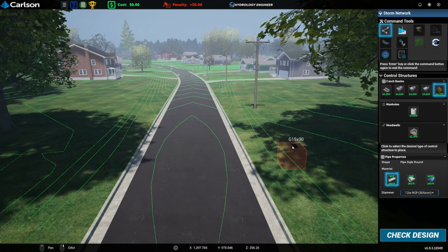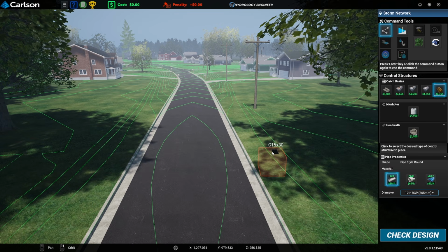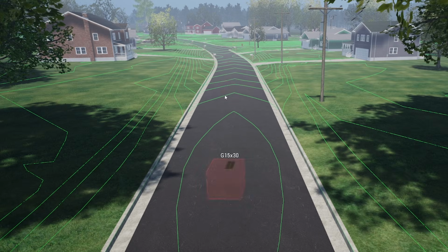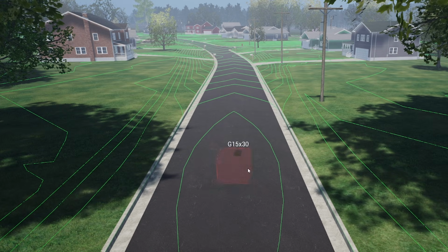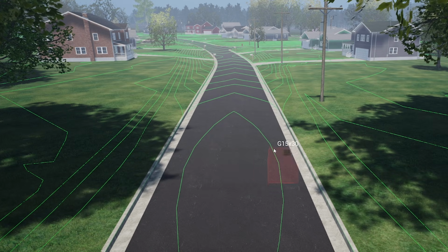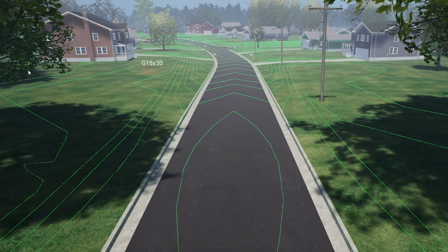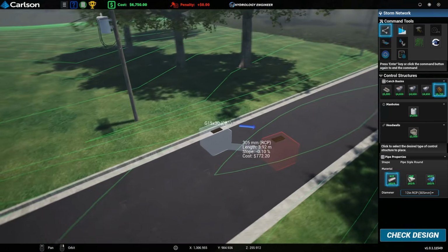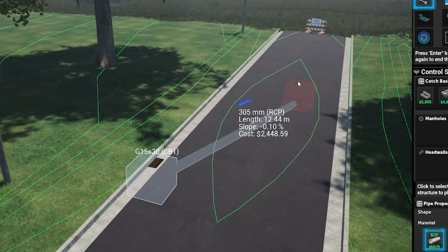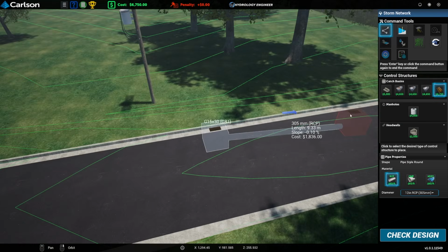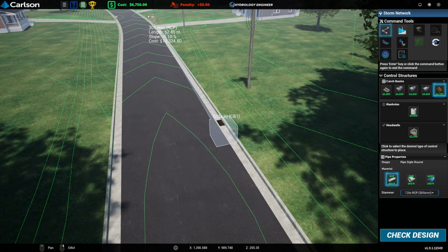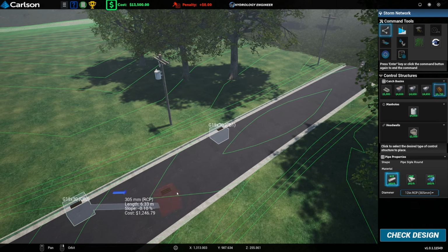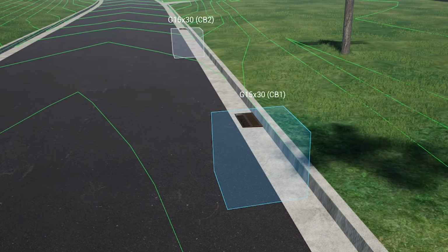And basically to do this step in real life, it's sort of separate from the pipe network. So we'd just have an Excel spreadsheet. We'd type in all the details of the road. So we'd have the falls, the contributing widths, contributing areas from the sides, etc. The type of grating and stuff. And basically, as you go from your high point, which as you can see from the contours, that's the high point, so this road is falling this direction over here, it would tell you where to space your gullies based on something called the flow width.